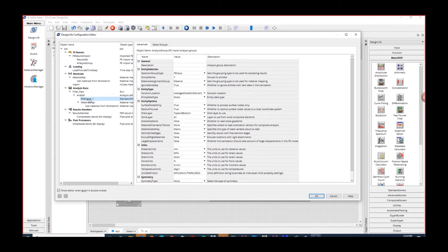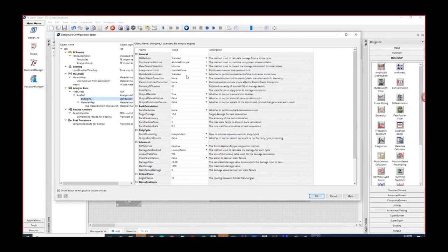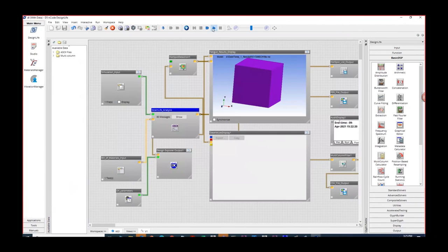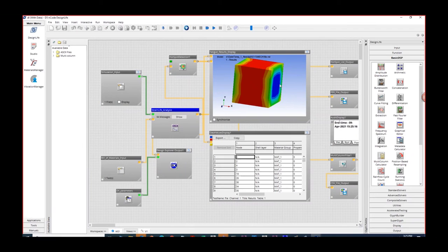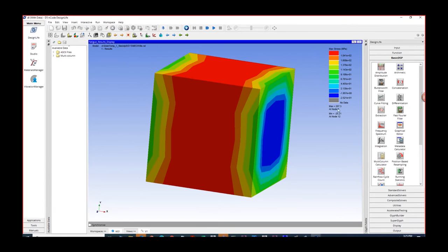Here in this case we have to use a plastic correction algorithm. I'm going to use Neuber here. So the results may not be valid, but here I'm demonstrating under what circumstances this becomes applicable. That's the point I want to demonstrate here. Because of the plasticity correction, the stress comes even below the yield. As I said, this corrected stress value is not right.